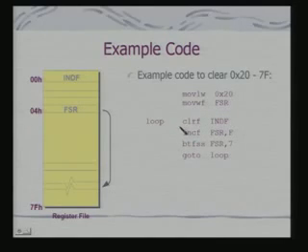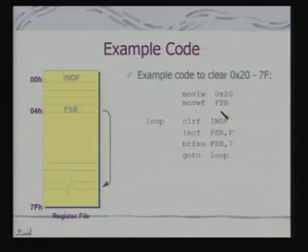And in fact, what you have seen is, interestingly, an application where indirect addressing is really required, because here you are changing the content of a memory location in a loop. So, you cannot really use the address directly as part of the instruction, because this address has to be constantly changed. At each step the address has to be incremented, and as we increment the address, we have to go back and clear the content. So, this is a simple usage of indirect addressing and how it is exactly used in PIC.